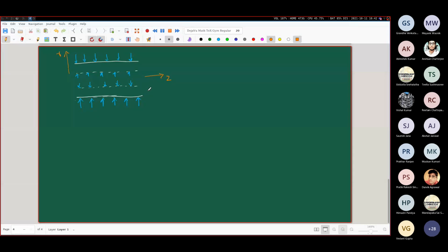The implication of that is that no matter what kind of a cross section of the pressure vessel you may consider along the z direction, all of those cross sections are going to look similar. Whether you take a cross section here or here or here, as long as you are not too close to the two ends, you are perfectly safe. So all of these different cross sections will look similar, and that is perfectly consistent with our assumption that there is no variation along the z direction.